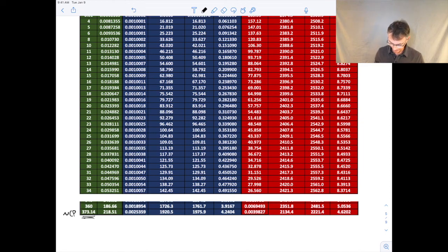Okay, and the reason I know it's not exactly it is because this should be equal to that at the critical point, because the saturated liquid line and the saturated vapor line kind of merge, so you should get the same value. So it's pretty close to the critical point, but not quite. That's why I used an approximately equal to the critical point.